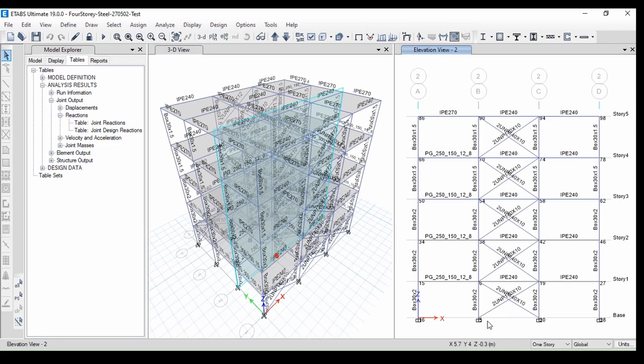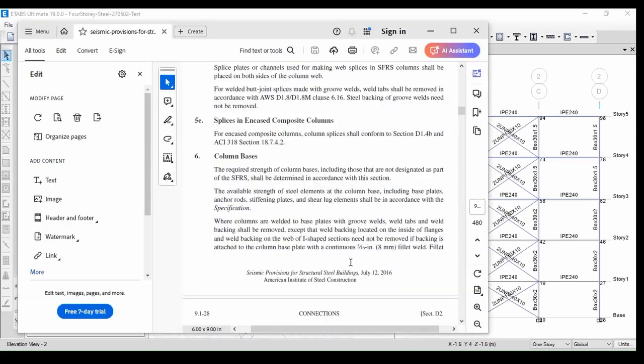according to AISC. In order to extract design forces, we get to the AISC code. They provided us a route to determine design forces. This is the section where you can find specific codes regarding column-base design, here in the Seismic Provisions for Structural Steel Buildings. Three different forces should be applied to the connection at the same time.